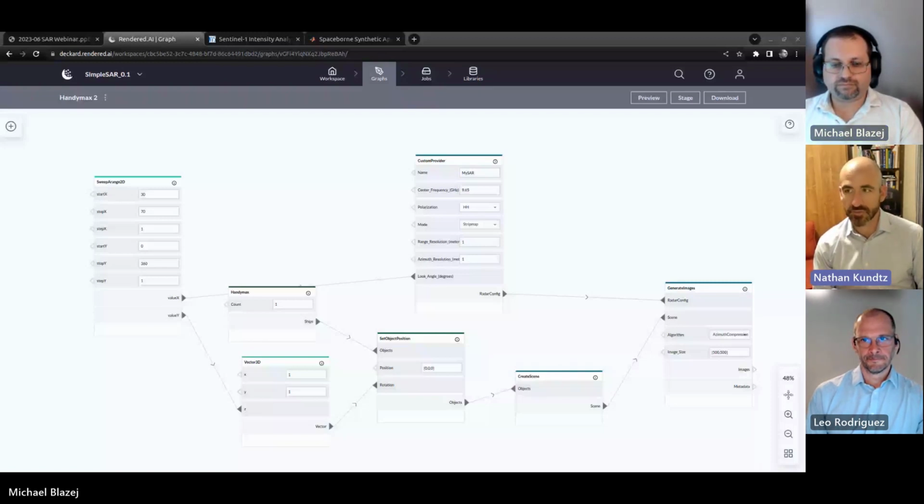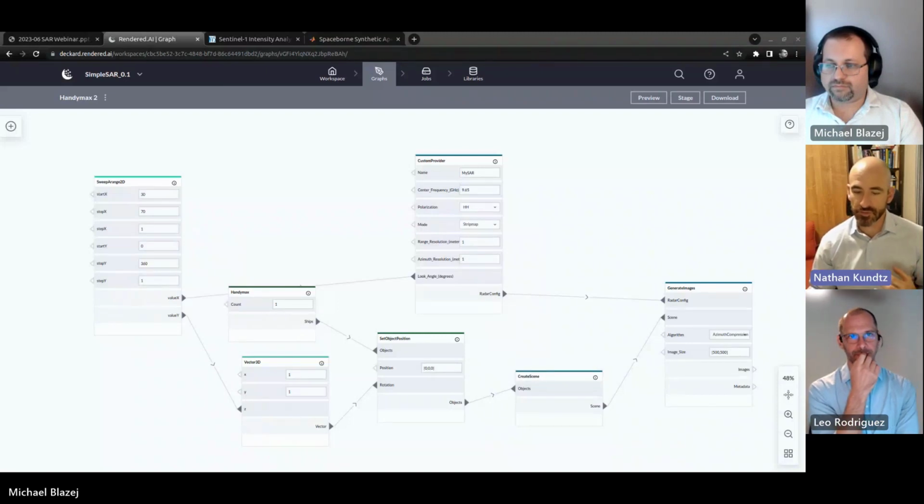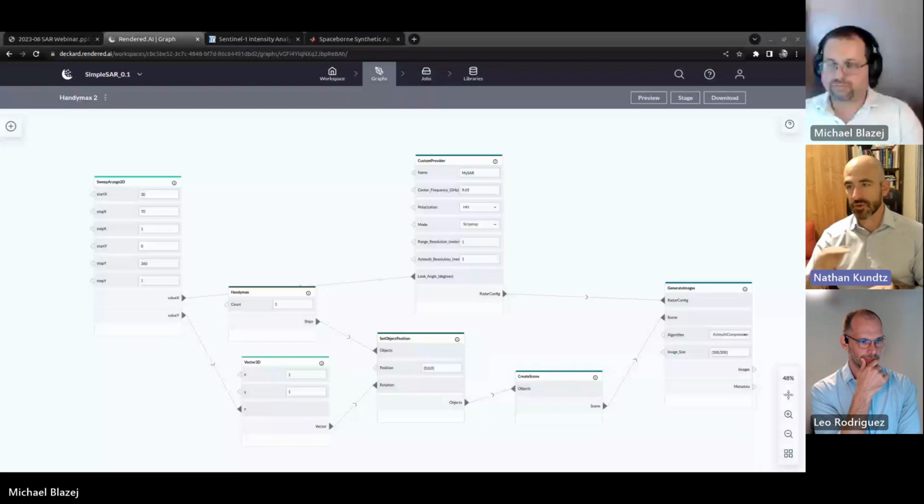And so you actually have to be really careful about how you simulate something like pavement electromagnetically, because you don't necessarily want to mesh all of the microstructures across that surface. If you look at a typical SAR response, in fact, surfaces like pavement look almost smooth in images.